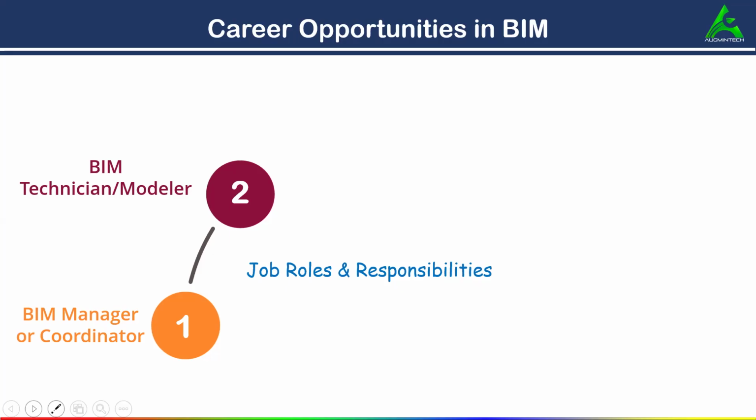Okay. And then what is your other responsibility? You have to incorporate architectural, structural, and MEP components into the model. Okay, collaborate with architects, engineers, and contractors to integrate design changes and updates. And you have to perform clash detection analysis to identify and resolve clashes between different building systems. So this is your responsibility if you are a BIM technician or modeler.